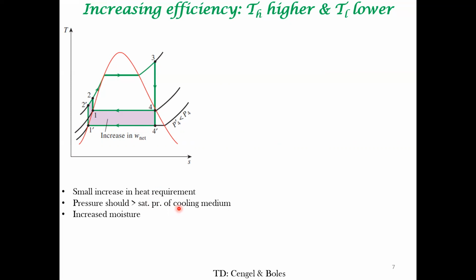So else you cannot really reject heat. Okay, so that is one of the disadvantages of this approach. That is, instead of operating at a higher pressure, you are operating at a lower pressure so as to have a corresponding decrease in temperature. However, this pressure should still be higher than the saturation pressure of the cooling medium, else the cooling medium will tend to evaporate, right?